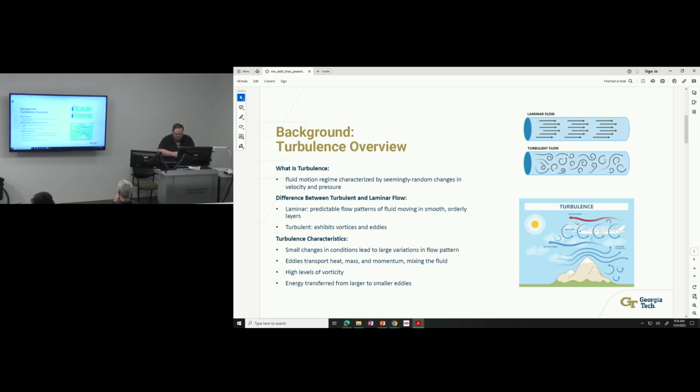In very large-scale geophysical systems, the stratification of the atmosphere and acceleration due to the Coriolis force restrict the vertical motion of the eddies. So turbulence can be modeled as taking place within 2D surfaces at any elevation, and I think chapter 13 of the textbook goes over that. But that's too large scale for what I cared about for this project.